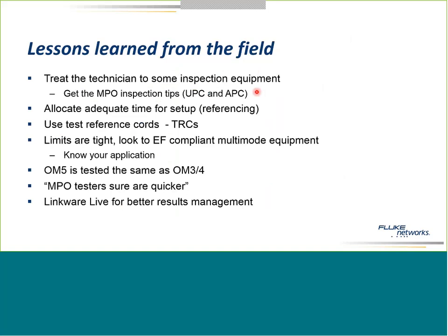Inspection equipment. It's not just cleaning. Please don't just take the dust cap or the end protector off of your patch cords and start cleaning right away. Inspect them. Make sure they're clean, especially with the MPO connectors. You got 12 options to go wrong there.